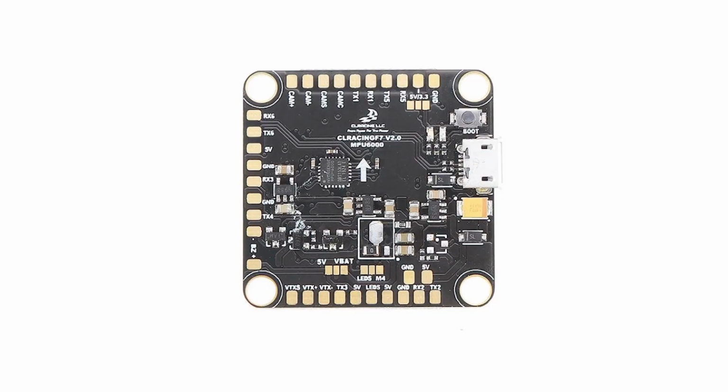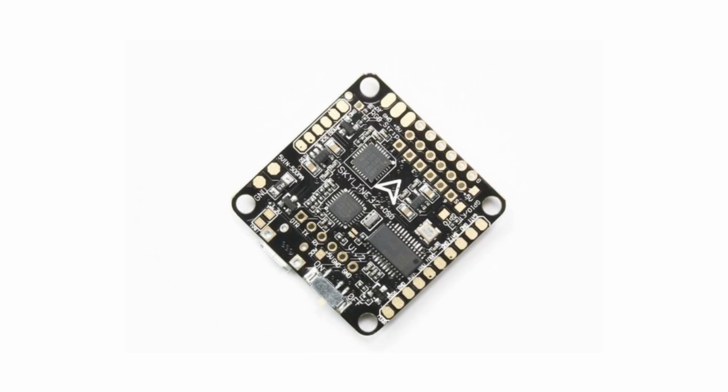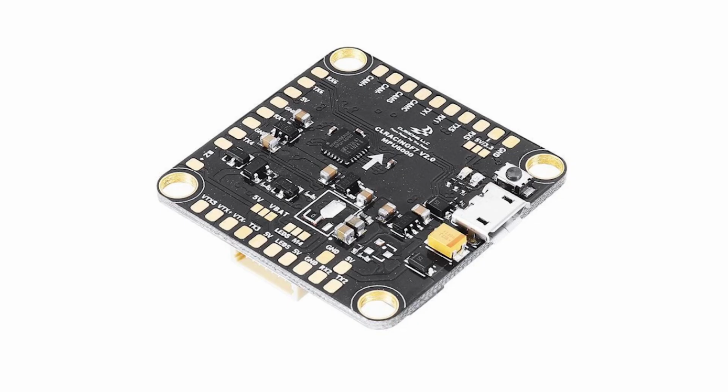of the drone. Flight controllers also have an orientation, meaning that there is a forward and backward already specified. This is usually indicated by a printed arrow on the board. It is important to pay attention to this when mounting the board.